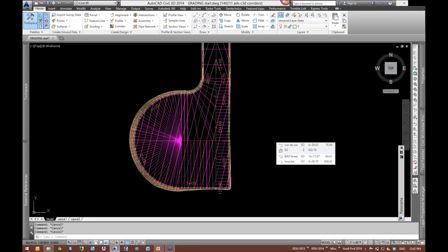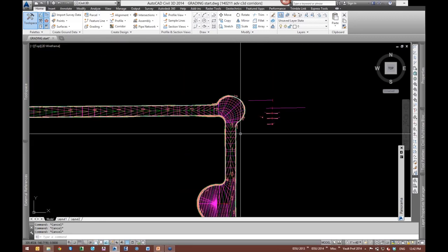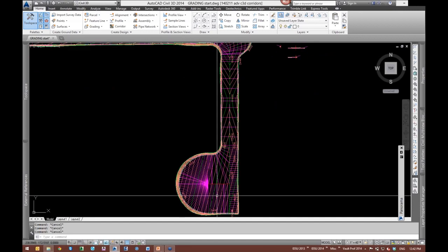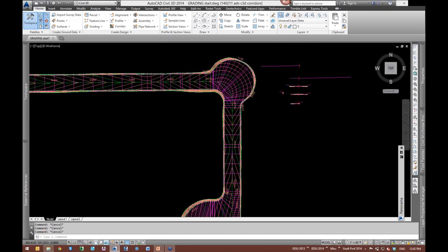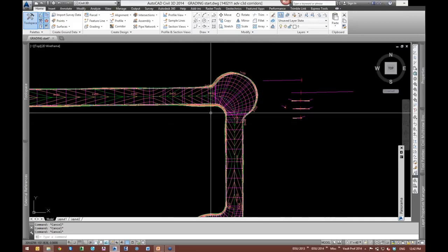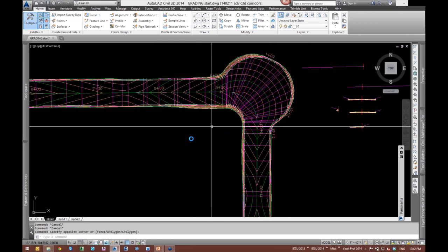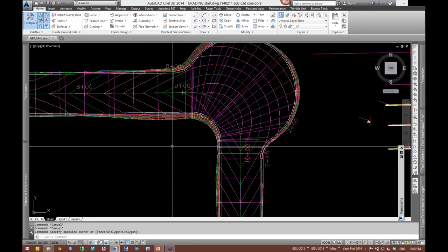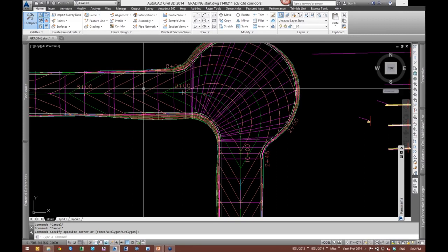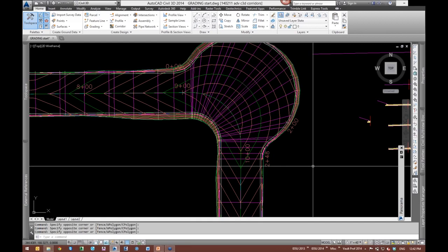Okay, so that's roundabouts. That's knuckle cul-de-sacs. That's offset cul-de-sacs like this. It's anything where the curb lines kind of have a mind of their own. Think about using this concept. And if you can, it should mean that your drainage concept, the drainage pattern, is based on your centerline alignment and profile. So next roundabout you're grading, think about some auxiliary corridors. Should probably make the job quite a bit easier.